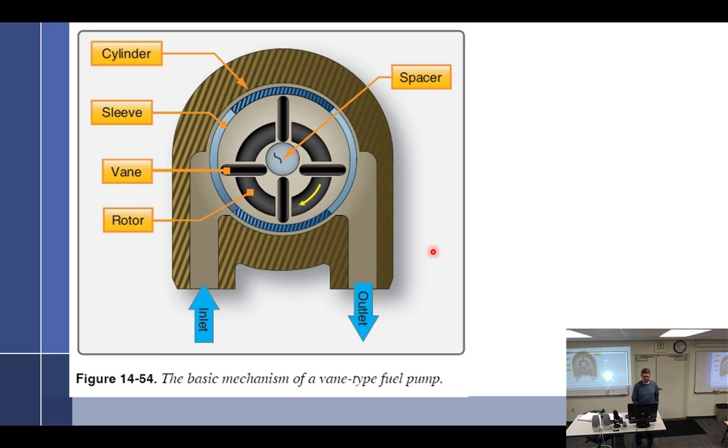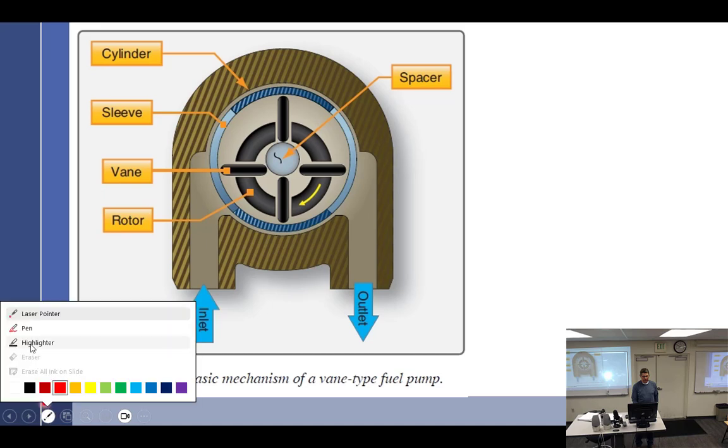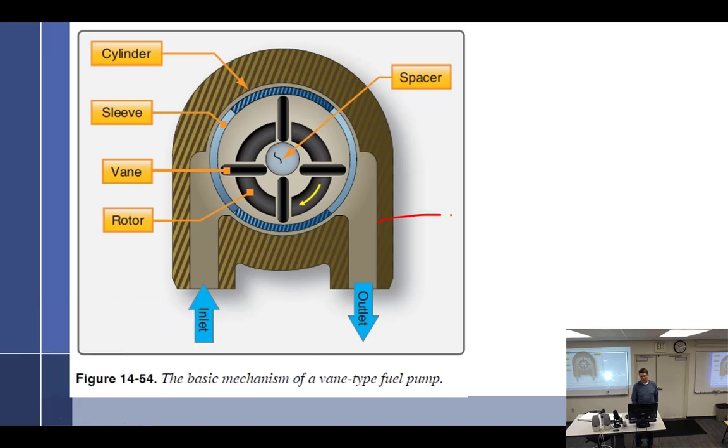Now, if I were to, let's see, right here. There we go, pressure gauge. Right now it's at 0. But if I put a little tiny orifice there, just a little bit, what's pressure going to do? This is going to go way up. If that orifice was too small, what would happen? What would break? Yeah, it's going to get too much pressure. This can only handle so much pressure in here. So something's got to give.